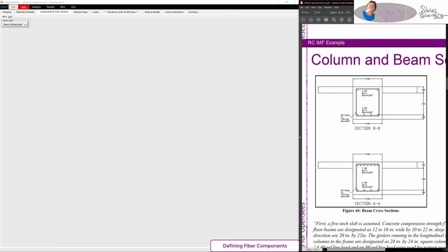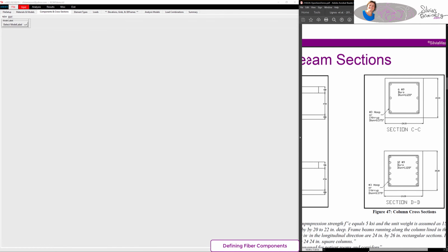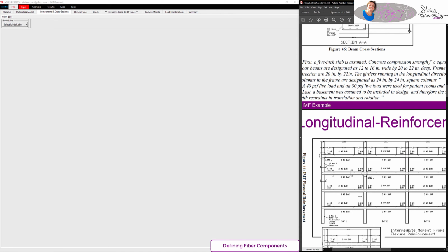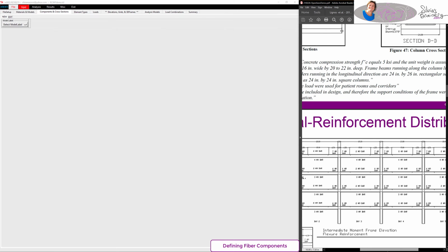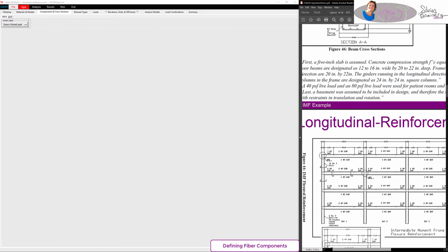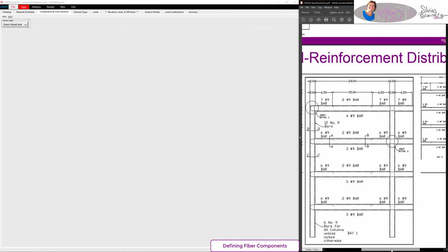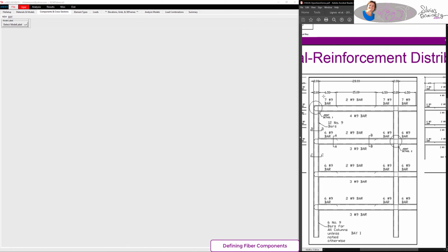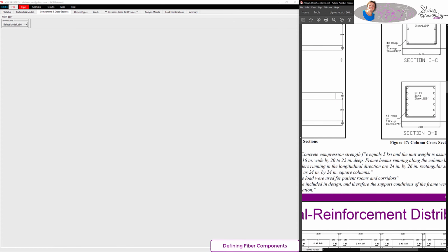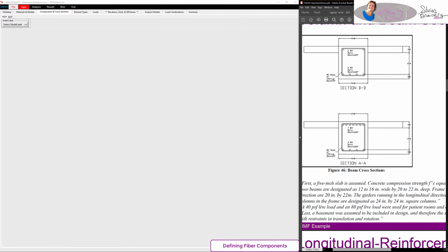What I then next do is define my fiber sections, and that's what's really nice about this layout that I have for this presentation. We're going to do the beams and the columns. For the columns, I defined the fiber sections to be symmetric in the two directions so that they're ready for loading when we go to a 3D model. But here's to show you that, look, different cross sections along the beams, and these are the different beam types that I'm going to be developing.